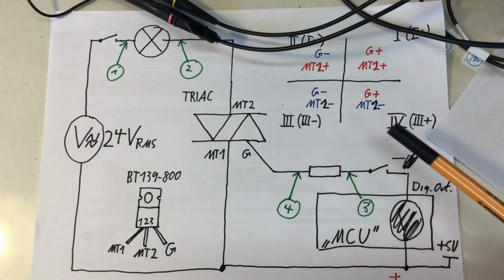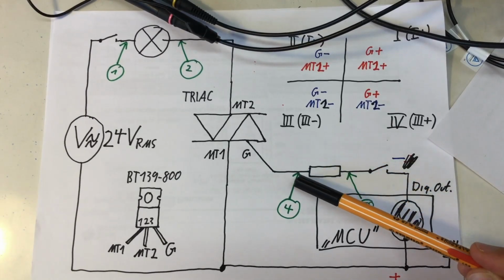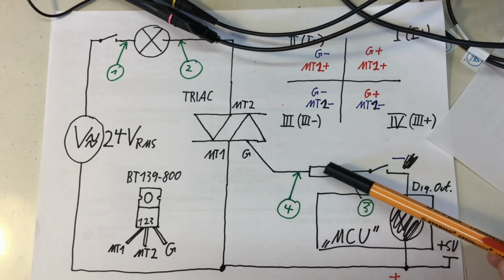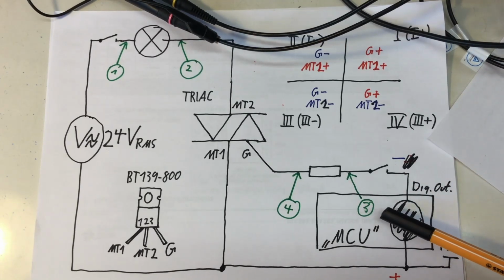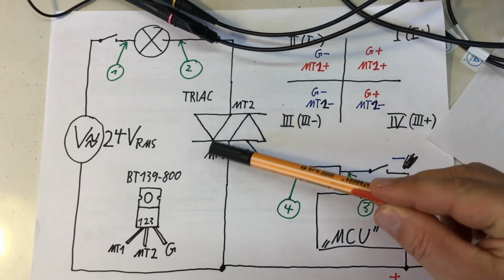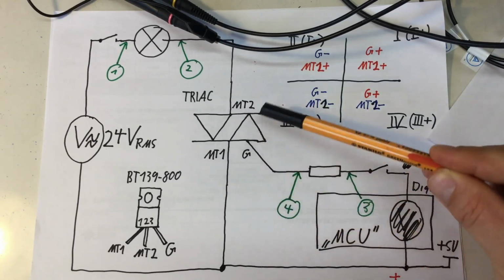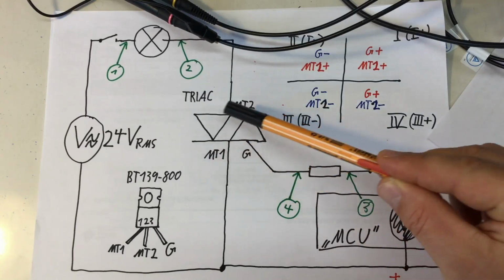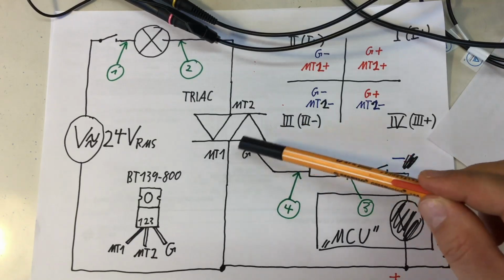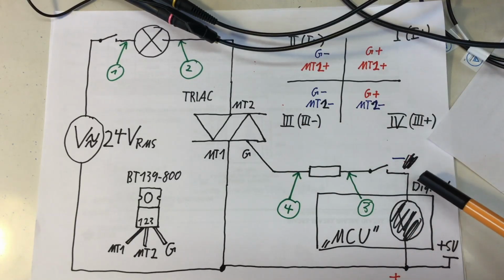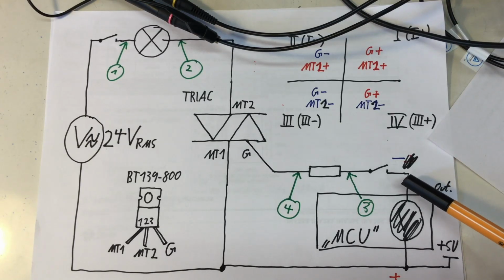And you really have to take that into account when dimensioning this resistor here, especially when you are using a low voltage microcontroller, say not 5 volts but 3.3 volts or maybe even less, because at some point the fluctuating voltage drop and also polarity reversing voltage drop across your gate will dominate the output voltage on your digital output.